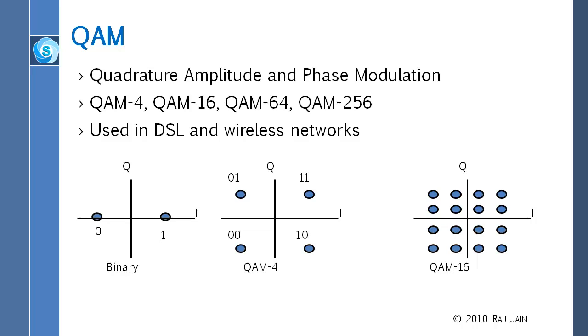So what is happening now is that all of these signals have the same frequency, but we are able to get so many bits out of that same frequency, a lot more bits, right? Because what is happening now? There is one more thing which I didn't point out here: this is a 4 by 4 matrix. But to get the 4 by 4 matrix, we have put 4 bits in each combination. So each of these combinations is 4 bits.